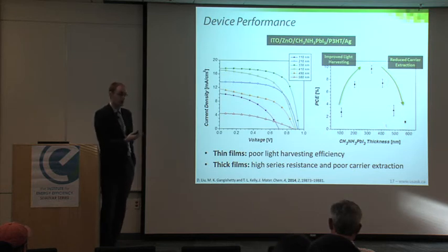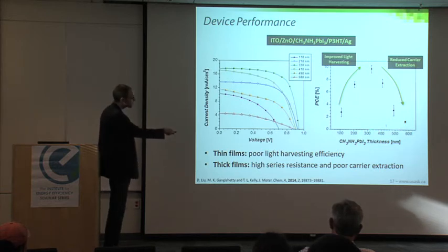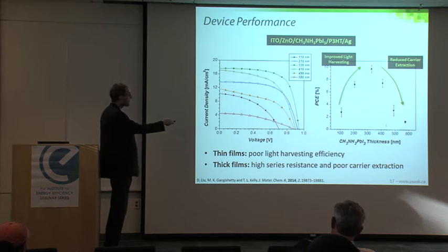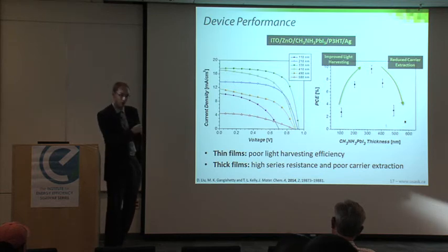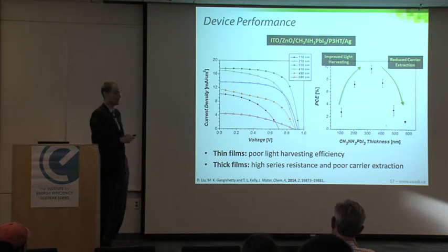And so we actually got very, very lucky in our first time out. With the solution processed films, we were sitting right at about 300 nanometers. Whereas if we had used a little bit more of a dilute solution, our efficiencies wouldn't have been 13 or 14. They would have been more like 9 or 10. I should also point out, as a young assistant professor for this follow-up work, I had switched to the more economical poly-3-hexylthiophene as opposed to the egregiously expensive spiro-OMeTAD.